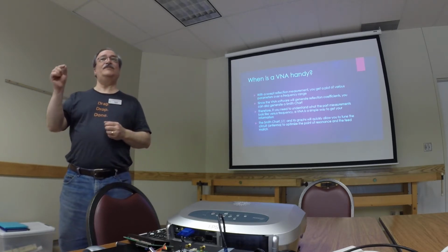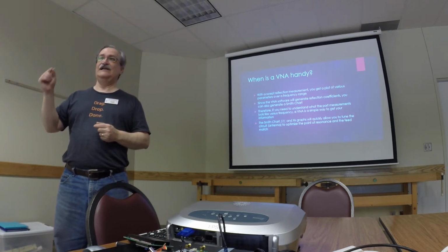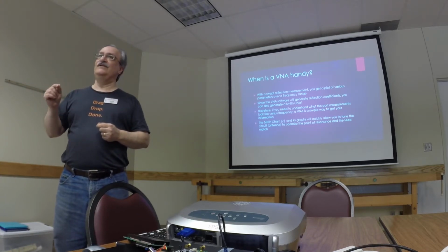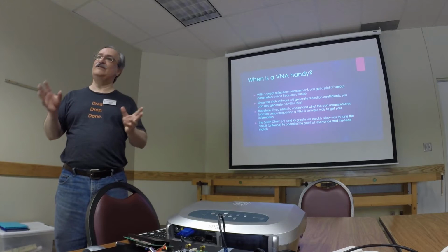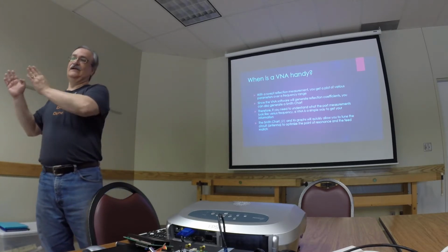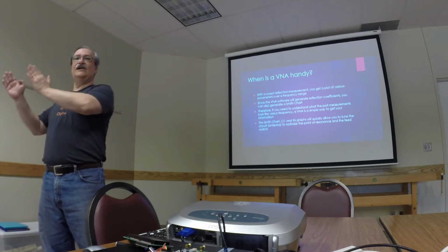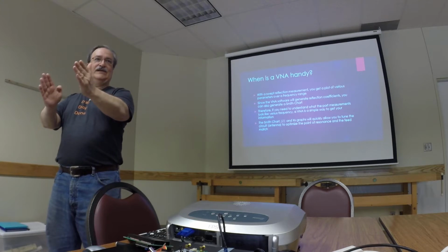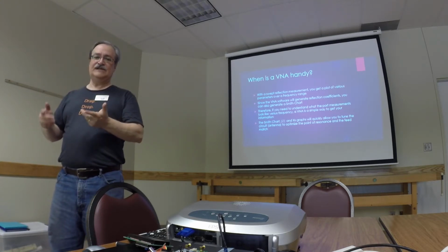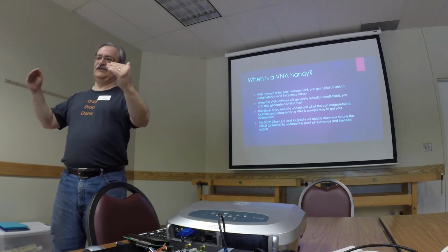The feed point impedance at 30 meters on an off-center fed antenna at 22 feet is much lower than a book will tell you. A book will say it should be around 200 ohms. And you'll see: cut it at the 25, 75% point, or cut it at the 1/3, 2/3 point, and insert your feed there.